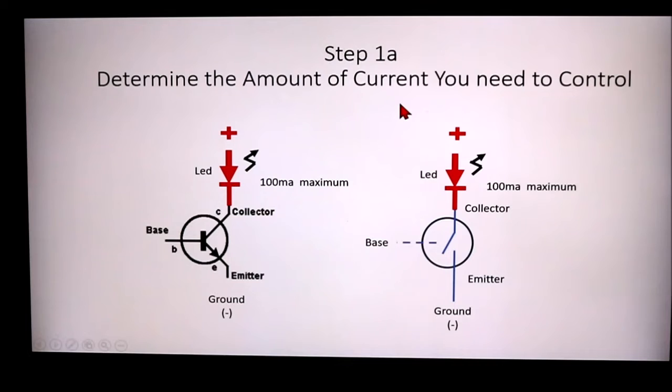Okay, so that's step 1A. Just remember that we still have to limit the current to the LED. Any LED, which is a diode, or regular diode, must have a resistor to limit the current, or the diode will go boom.